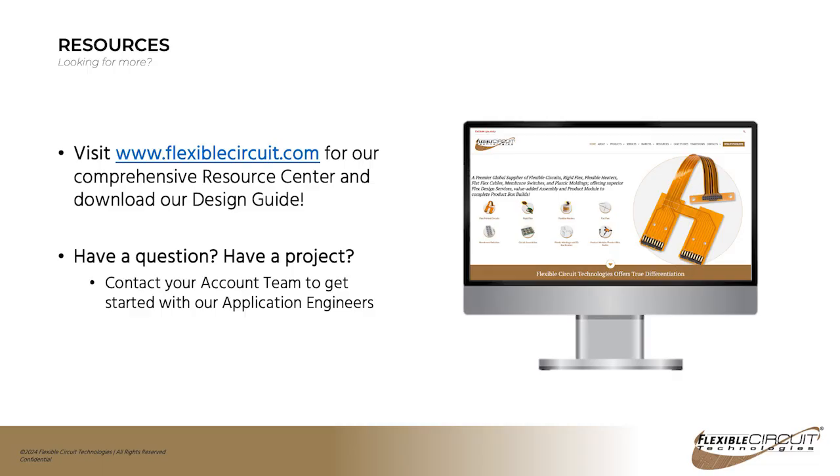Well, we'll start with the common sheet sizes. Material, it depends on where you're getting your material from. Some manufacturers will supply the material in 24 by 36 inch sheets, and a lot of the Asian suppliers will supply it in rolls that are anywhere from 250 to 500 millimeters wide and then continuous length. And so it kind of depends on where your circuit is being manufactured on what those standard panel sizes are. As far as the standard panel sizes, every manufacturer has different panel sizes. In the U.S., I can tell you that 12 by 18 is common, 18 by 24 is common, 12 by 24 is common.